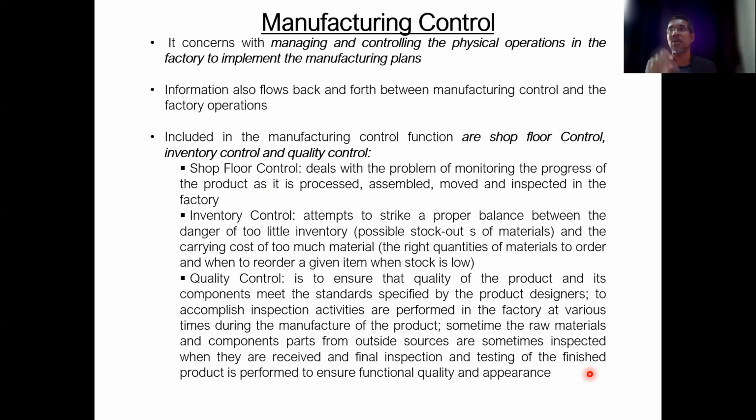It was not tightened but had dropped inside. That became a big problem because when the alternator is spinning and running, the rotor inside will cause a short circuit and burn the alternator. It is good to detect this early. If not, there might be bigger problems, like burning.